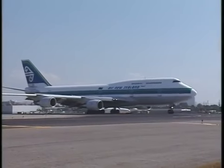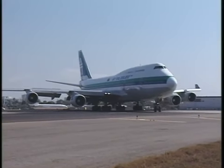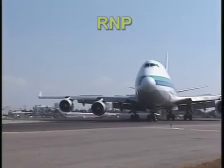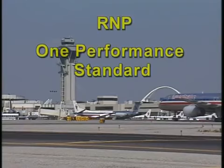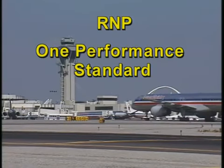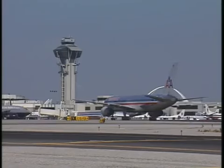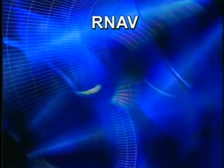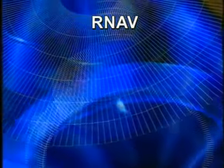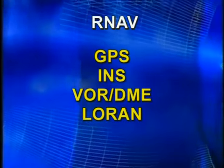To capitalize on the potential of these new technologies, the FAA, in conjunction with the International Civil Aviation Organization, ICAO, has introduced a new standard of navigation and airspace management called Required Navigation Performance, or RNP. The theory behind RNP is to establish one performance standard that applies to aircraft, airspace, pilots, air traffic controllers, and international aviation authorities. This single performance standard is enabling the widespread use of area navigation, or RNAV. The term RNAV no longer refers solely to the VOR station mover of the past, but rather encompasses several different types of navigation equipment. The heading RNAV applies to GPS, INS, VOR/DME, and LORAN-based navigation systems.